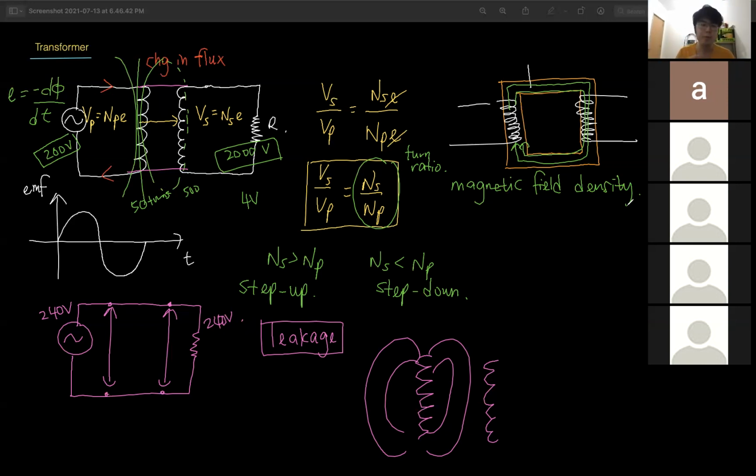Now, one more thing. Here on the primary coil, it must be AC. Why can't it be DC? Because with DC there's no change, right? The current is the same. Fixed current, fixed voltage, 6 volt and it's 6 volt. If it doesn't change, meaning the magnetic field doesn't change, then there's no induced current produced. Then the transformer is meaningless. So you must use an AC current.